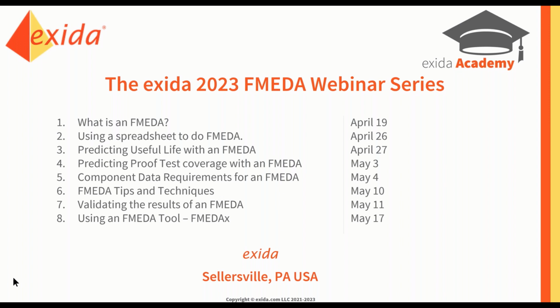You may have devices within your safety function design where the useful life is significantly less than the mission time, in which case your maintenance program should be set up to replace or refurbish while you're within your mission time. You also may have devices where the useful life is much longer than the mission time, in which case you don't have to worry about it. Now, when does a mission time end? Usually when they decide to scrap or stop operating the industrial process.